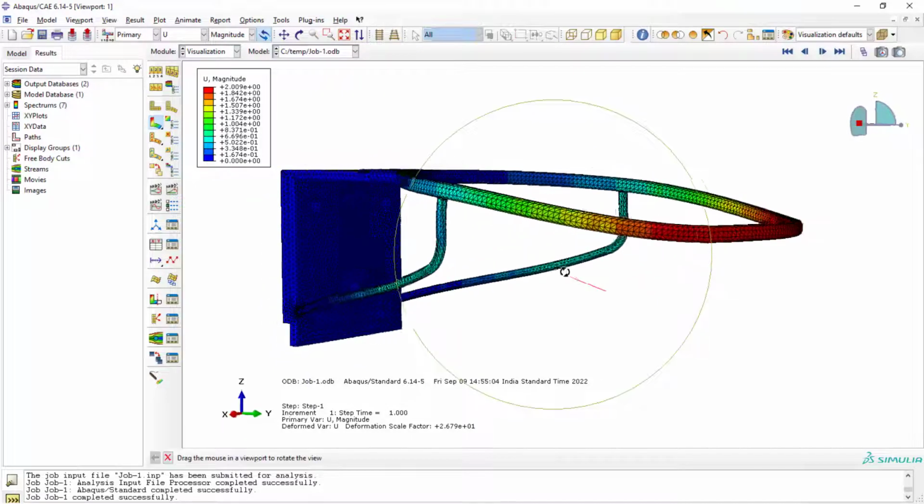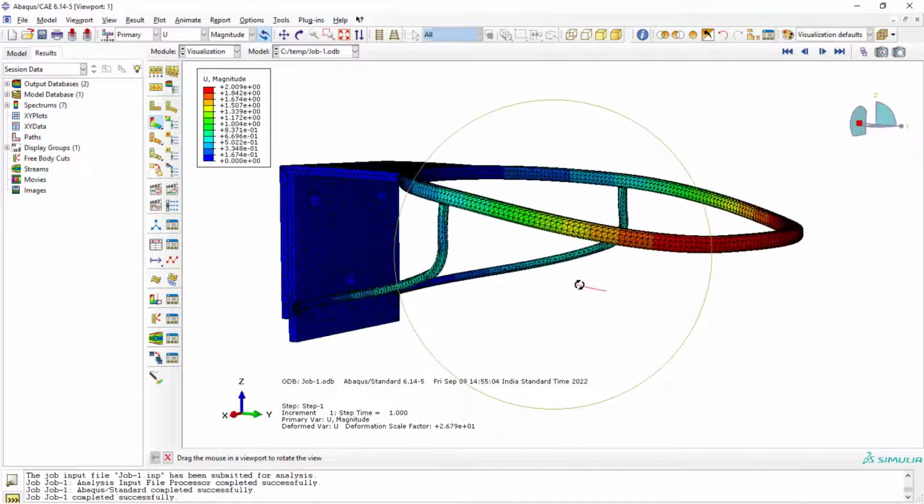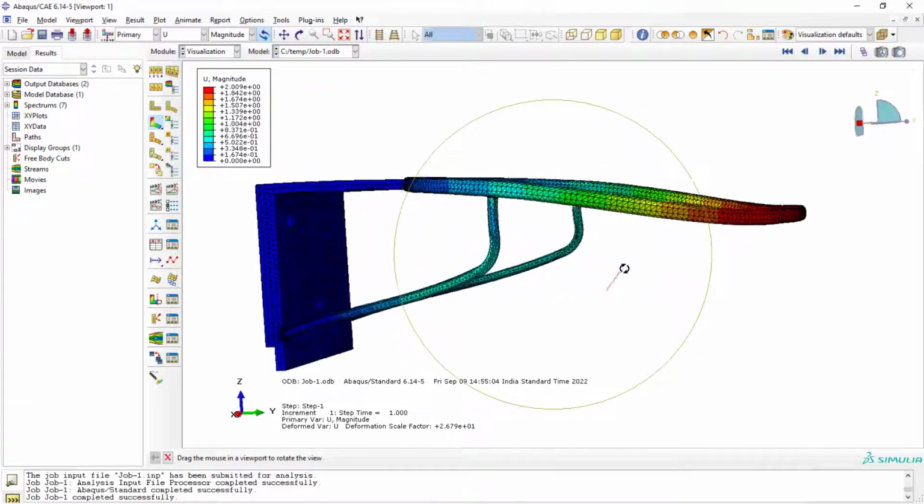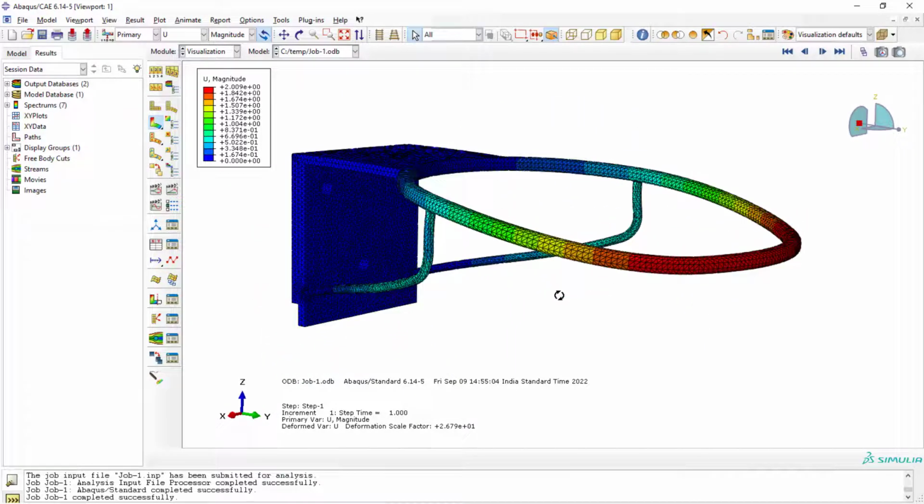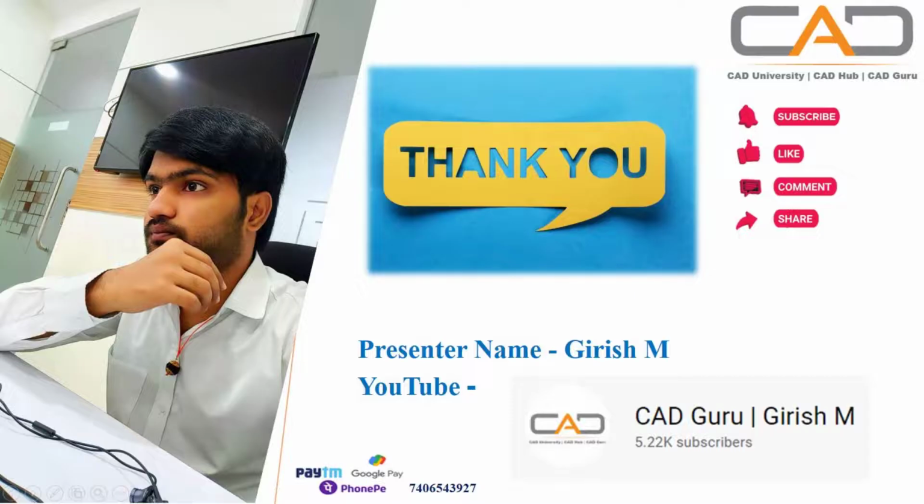Okay. Yep. That's all about this session. So if you get this kind of error, that is error element missing section, this is how you need to deal with it. So simply add the section into your analysis process.